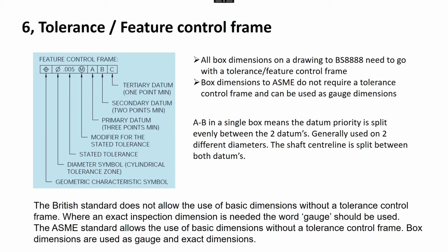One thing to note as well, generally speaking, the ASME standard uses dots as the decimal marker, and the ISO standard uses commas as the decimal marker. So if you don't know what standard a drawing's been done in accordance with, and you've looked all over the drawing and still don't know, if it's got commas on there, it's usually the ISO standards. If it's got dots on all the dimensions, it's the ASME standard generally.